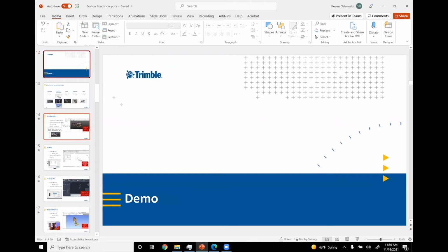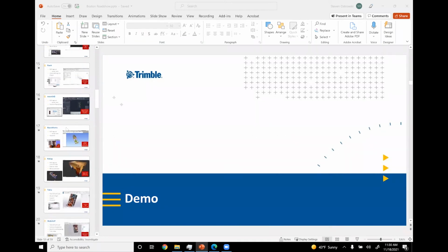That's generally where the workflow is a lot better, especially with the georeferencing. You're able to do that live, out in the field. Generally with those other scanners, you would still need to georeference or put targets up and do kind of an RTS workflow as well, whereas the X7 is doing it all together. You can either resection with the X7 or you can manually place it to the model as well.